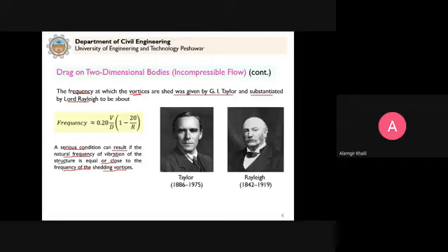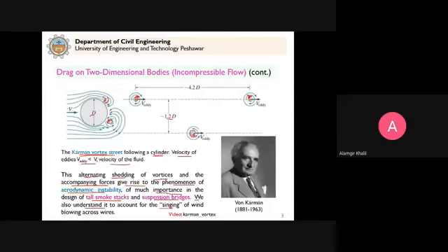It says that if the frequency of vibration of the structure, which you might have studied for suspension cables and bridges in your structures course, or studied in physics at school or college level, so the same we deal with here. If the natural frequency of vibration of the structure is equal or close to the frequency of shedding vortices, then this will result in a serious condition. Clear? Because we already studied that this phenomenon is known as aerodynamic instability, and we consider it in the design of these structures.